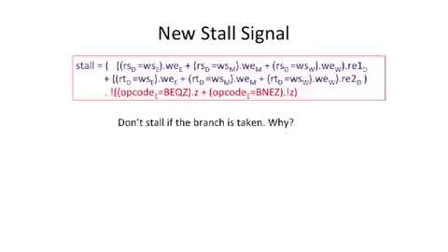These are the RS and RT in the decode stage against the other stages in the pipe, the execute stage, the memory stage, and the write back stage, and make sure that you're both reading the registers and you check the write enables to make sure that the respective instructions in the different pipeline stages are actually writing to the different locations.